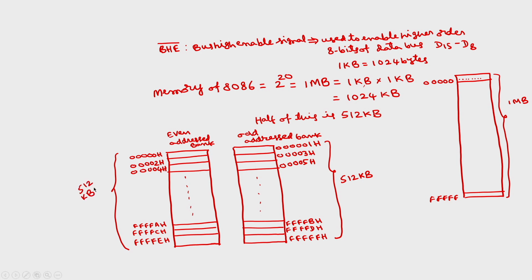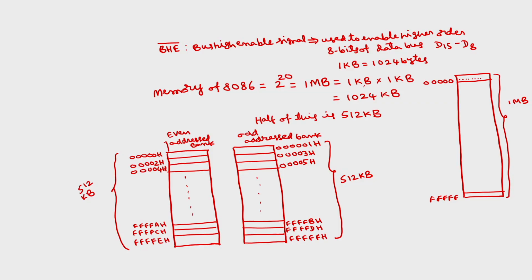So, each memory chip will have some chip enable signals. In order to select this particular chip, we require some chip select signal. After selecting the chip as a whole, we will select the particular location. That is how the memory read or write operation has to be performed. To perform either a read or a write operation, there will be a chip select signal corresponding to each memory. Normally these are active low signals.